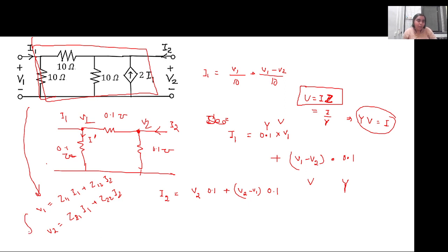Then, when we add a 20 ohm resistance on the output side, we will have the condition V2 equal to minus 20 into I2. In these two equations, we can input this condition and calculate V1 by I1. I have solved it the way you solve a network analysis. You can write separate equations for the two-port and then solve the circuit. It is totally up to you.